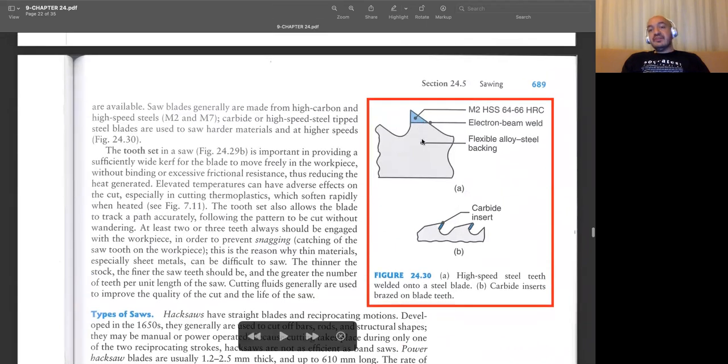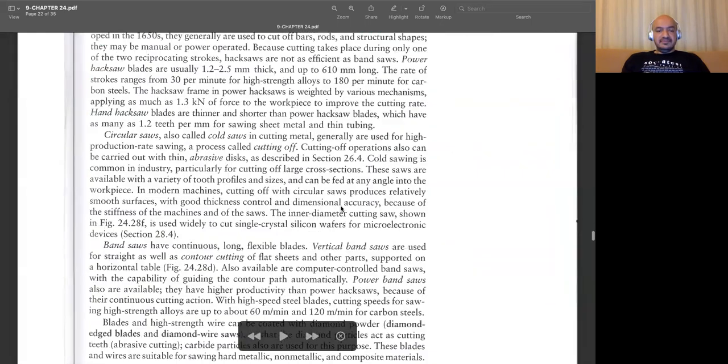And if the workpieces you are going to saw have higher hardnesses, then you may use special saws which actually have special inserts at the tip of their cutting edges. You may even replace these inserts or do some coating on the cutting edges, and with the help of these inserts or some coating, you may use the same saw for a longer time, and you can do sawing on very hard workpieces.